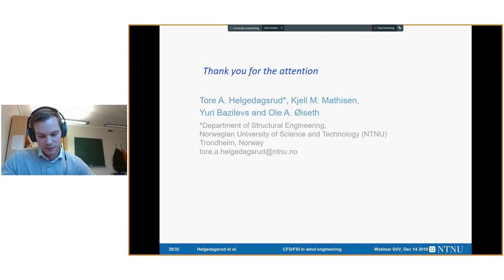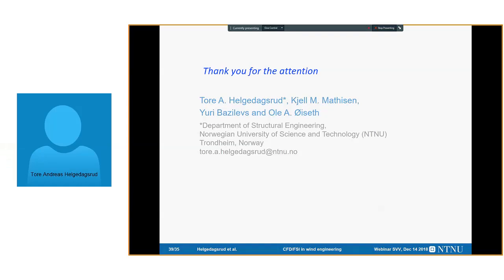Well, thank you for the nice comments. This is a result of the finite element modeling. It allows us to use this dynamic mesh, and I don't know if you use the same, but we are really just solving the elastic equation for the fluid. There are no dynamic things to the mesh other than the boundary conditions of the motions of the structure. We just pass it to the solver.